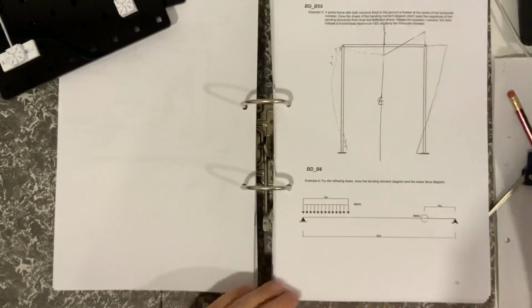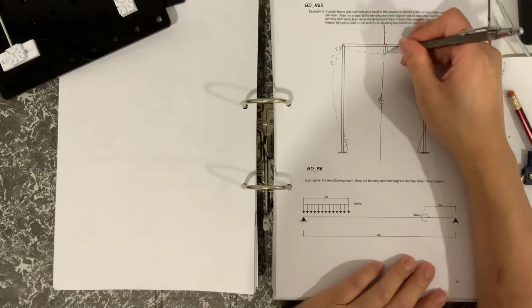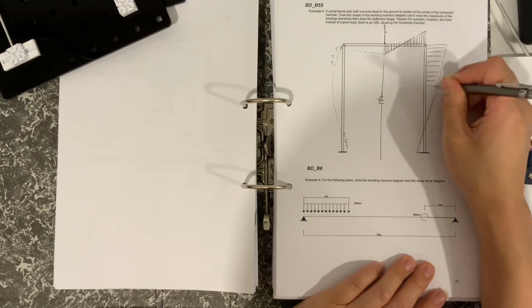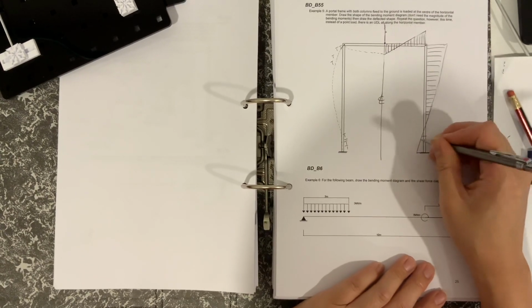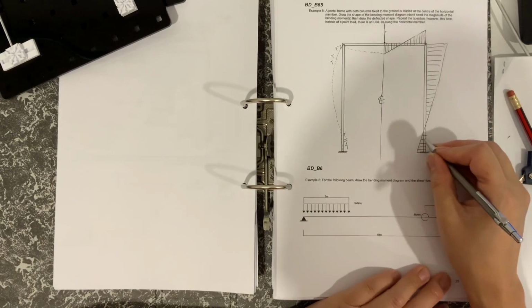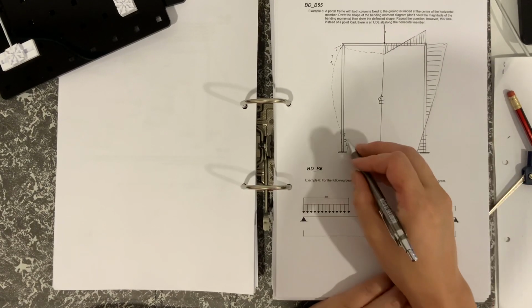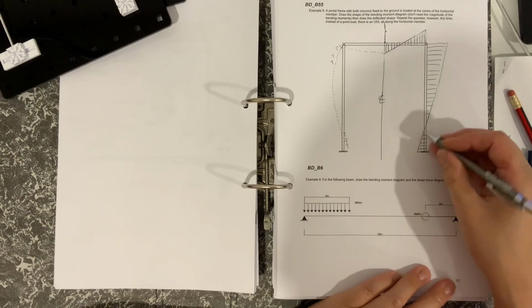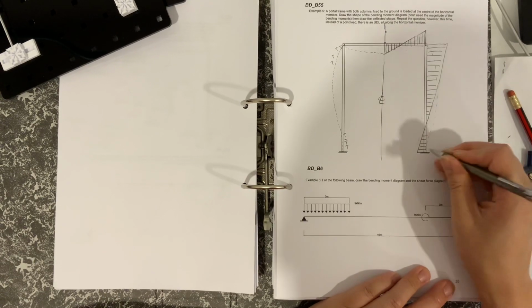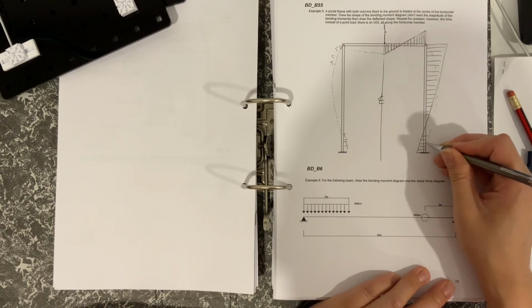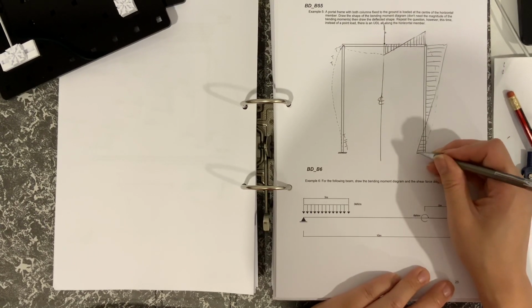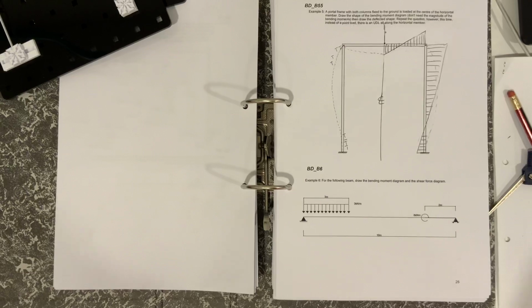Alright, so the bending moment diagram, I'll give that a bit of shading so you can see the bending moment diagram there. Okay, and then the bending moment is plotted on the tension side, so you can see the tension side there. So this side here, if it was deforming round, would be like that. The inner side here, remember that's a mirror, would be the tension, so the bending moment is shown on the tension side.